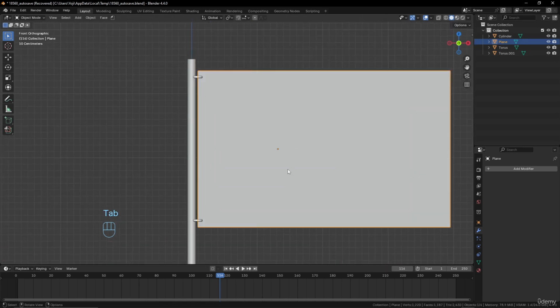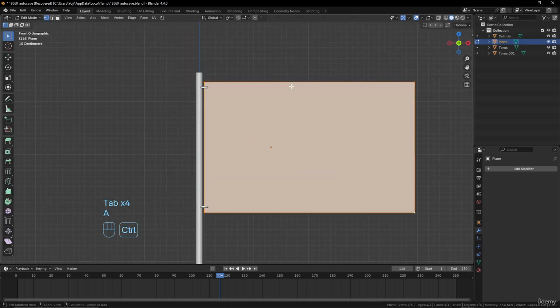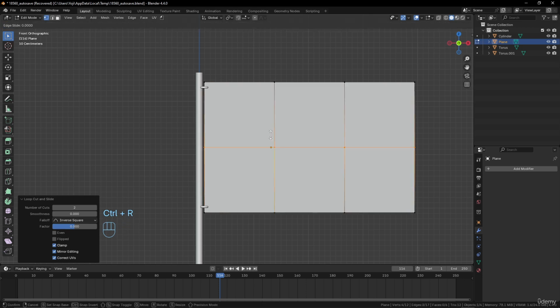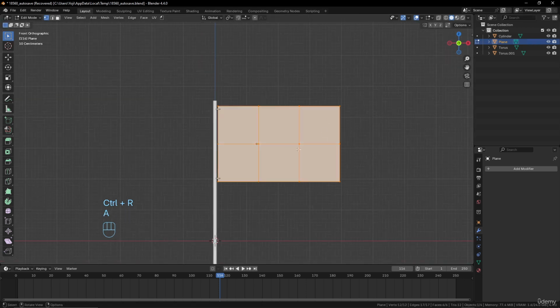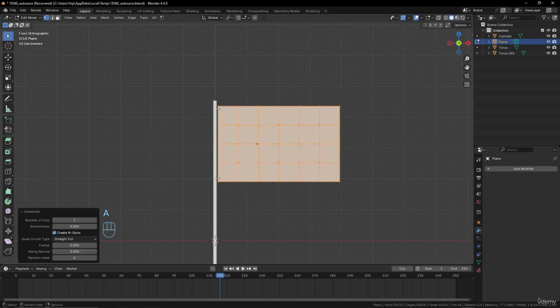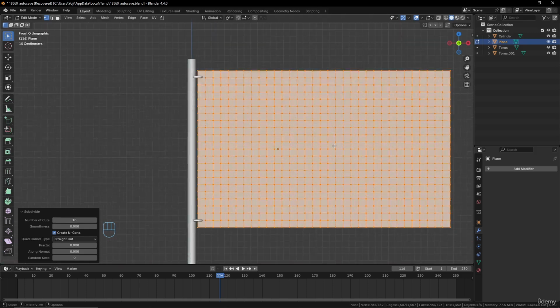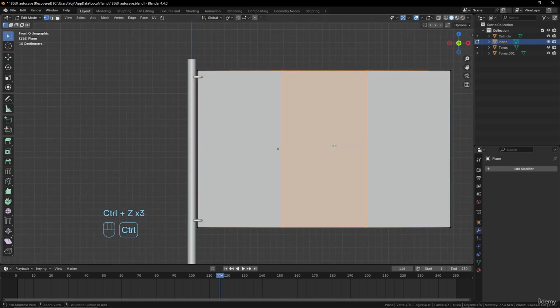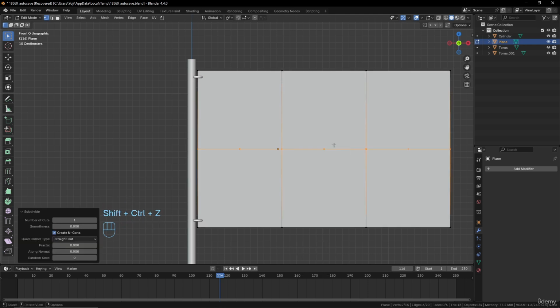we want. Okay, so now as I told already, I need something more squarish, so I will subdivide by 2 here and by 1 here. Like this, I will have squares, and I can subdivide this mesh a few times, maybe until I have this kind of definition. I mean, you need to have enough definition to work with, so maybe I will just make a subdivision simple